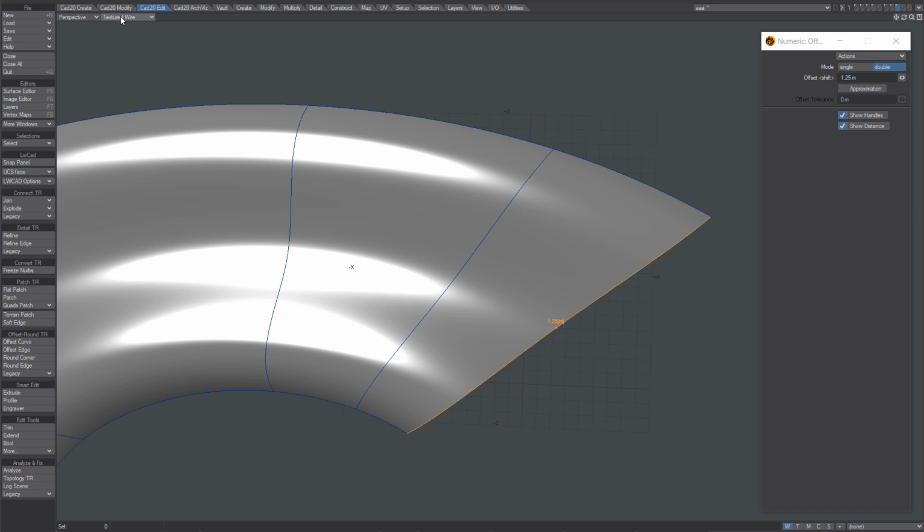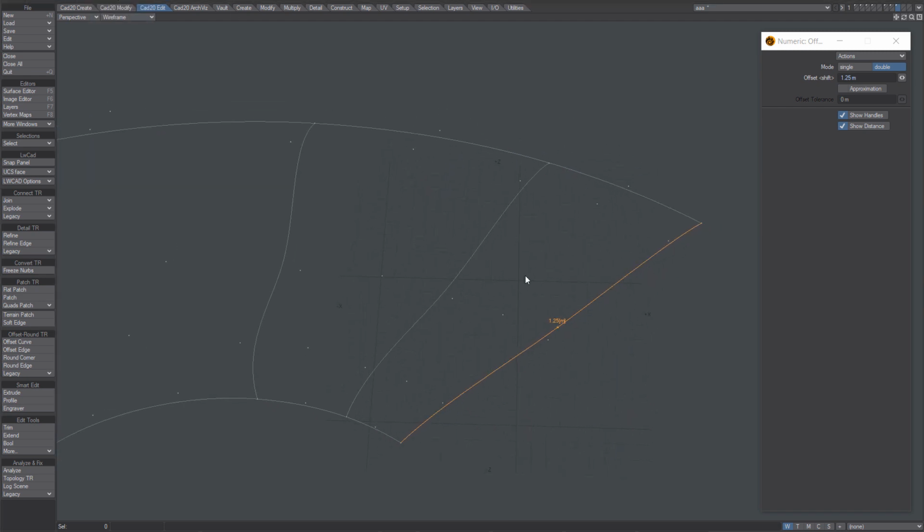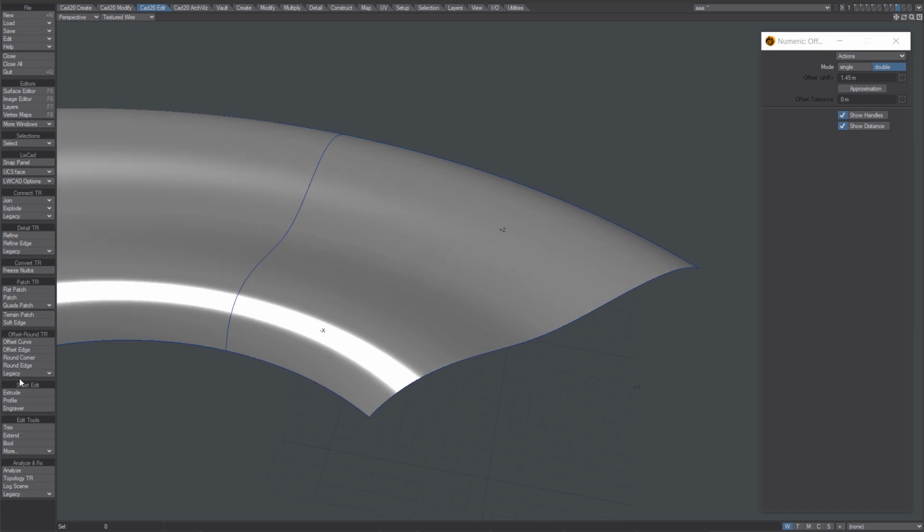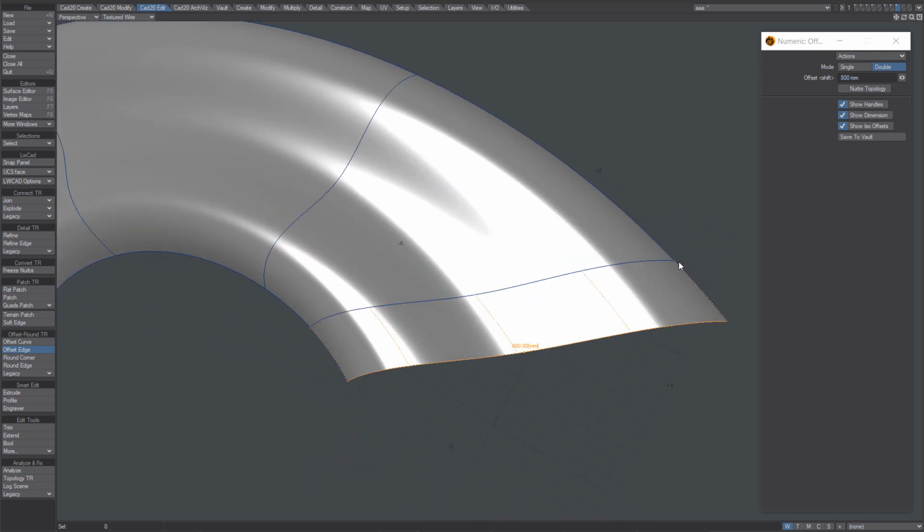So this was just a simple trick, and it was done this way because this operation is very simple and very precise. If you split a NURBS surface into two pieces, it is a pretty standard operation, and there are no problems with this. But for real offset, it is much more complicated. So if you use the new offset edge tool and offset this edge, you can see all offsets along ISO points are identical.